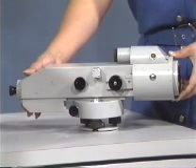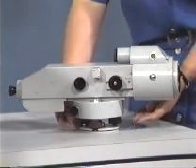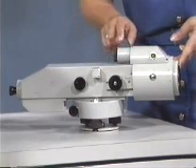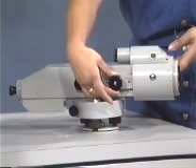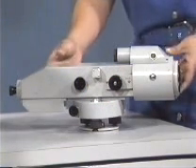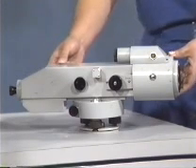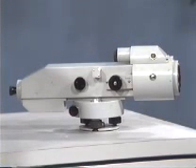This is a Zeiss NI1 pendulum level. It looks and functions the same as the level that was previously shown, with an exception: there is an addition of a micrometer with an eyepiece. The micrometer and eyepiece is an auxiliary device to provide the measurement of very small increments. With a first order level rod, the increments can be read to 2/10,000ths of a meter.